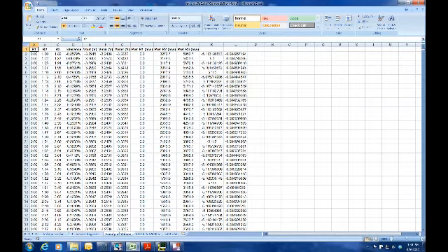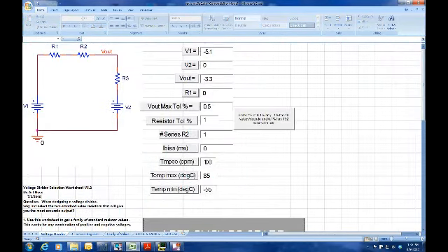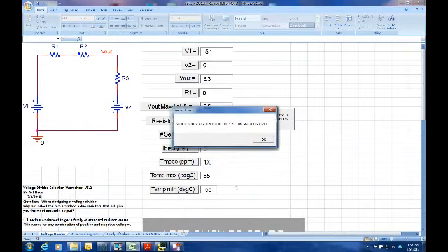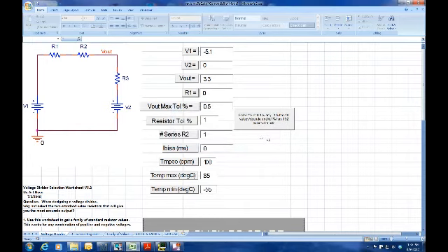But let's suppose that we put in a negative voltage and we're looking for a positive voltage coming out. It should give us an error, which it does. It says V out must be greater than Vn and V out must be less than V2. No solution to this problem, because you can't get a positive voltage from a voltage divider putting in a negative voltage. And there's other scenarios that go in here. It's a 4-quadrant problem, and helps keep you from making mistakes. It will give you errors.